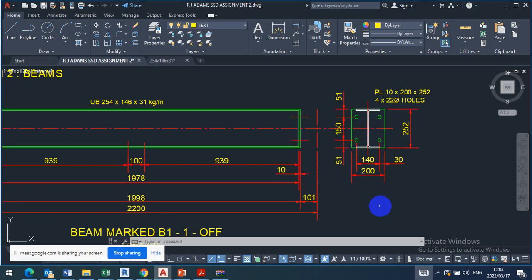So they are saying recommended minimum is what? 70. So if you use 2 times, like 150, 140 is fine. You know what he has done? He was assuming that because this beam is too long, the height is too much. So you can't use here 70 and 70. They'll be too close to the center line and you remain with a lot of material there. Otherwise, what you can do, you can have a hole here at 35 from the center line, another one here. But it means you have to reduce the size of the end plate. You understand?